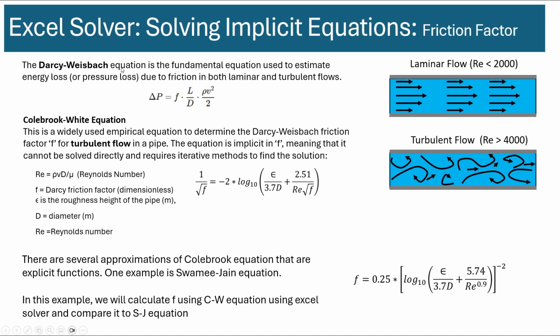So without further ado, let's try to estimate this friction factor for a set of fixed conditions, and compare that with the Swamee-Jain equation and see whether this equation is a good approximation of the Colebrook equation.